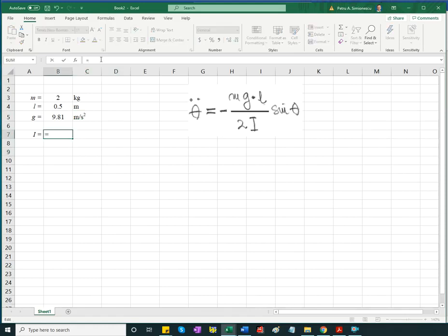And then calculated. This is where an equation goes, and I have again the mass moment of inertia about one of the ends. It's calculated with the equation. The mass. Oh, I'm sorry, I want to do something before that. I want to label. So you may want to pay attention here. Some of you may not know this. I'm going to give names to some of the cells to make equation writing and debugging easier. So cell B3, where the mass is given, some red are inputs. I'm going to call this M, and I wrote M here. Enter.